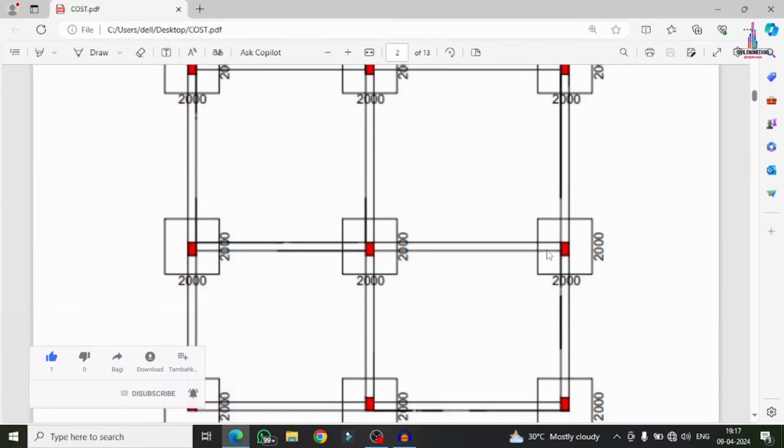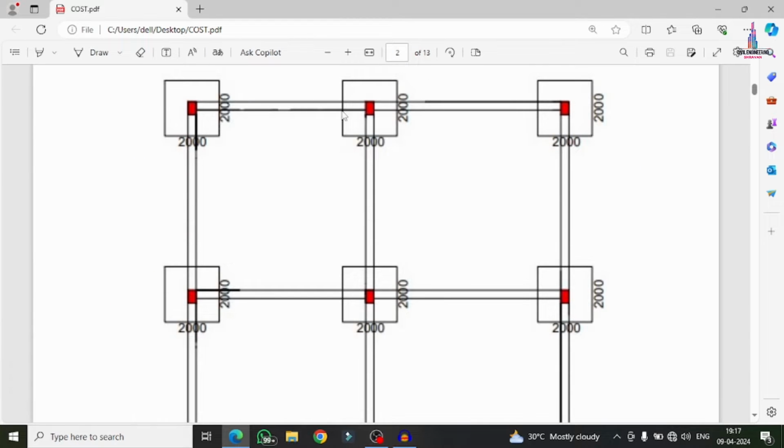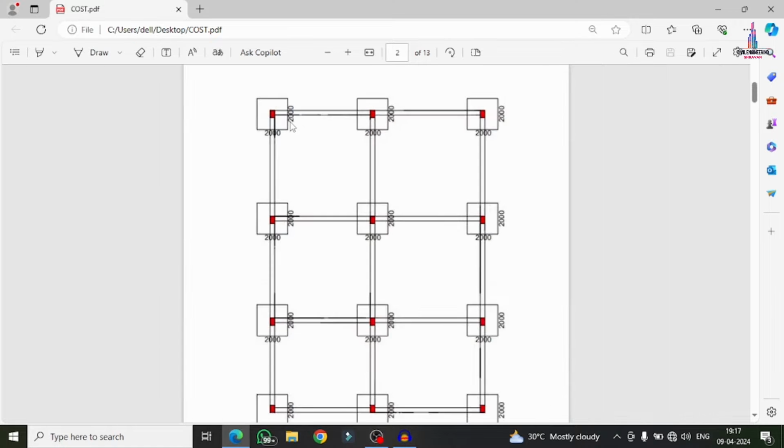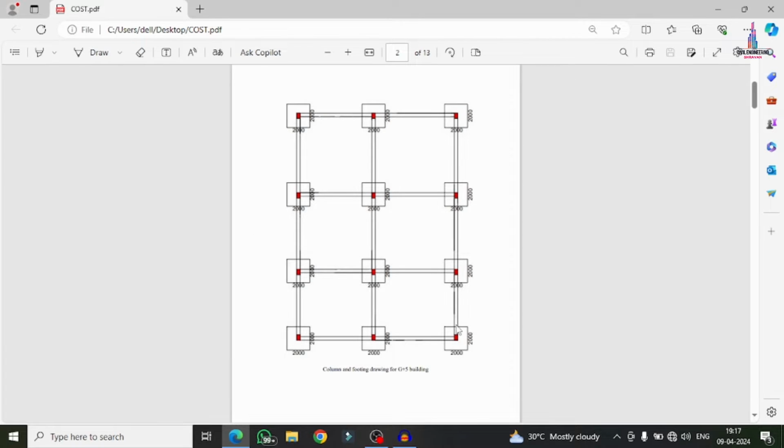Okay, so as per the typical floor plan, it will have joints here. Now we can see this is the L joint, this is the T joint, this is the plus joint. So it will consist of approximately 4 members of the L joints, 6 members of the T joints and 2 members of the plus joints here. Okay, so for calculating the center line distance for L joints, no need to take any correction.